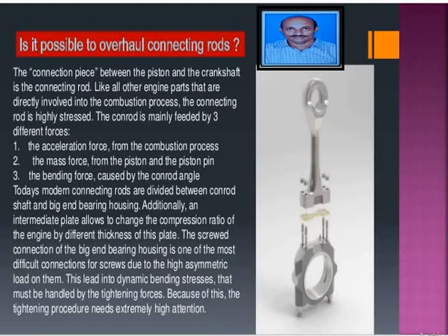and this load acts at very high temperature and high pressure. Even so, the screws, nut and bolt arrangement should be in a proper pattern. If it is not a proper pattern, it will lead to dynamic bending stress that must be handled by the tightening forces. Because of the tightening of the nuts and bolts, there will be extremely high tension, because we are tightening the connecting rod.